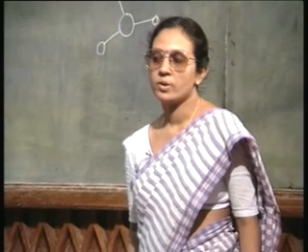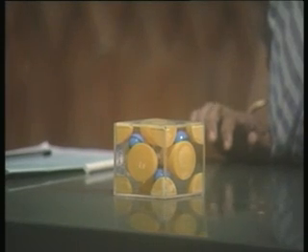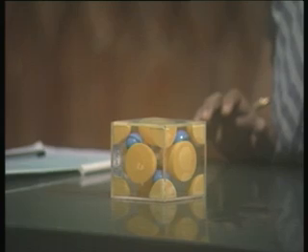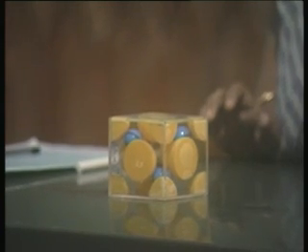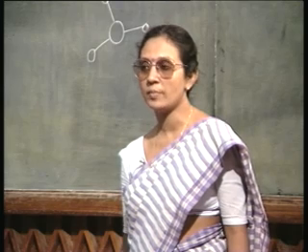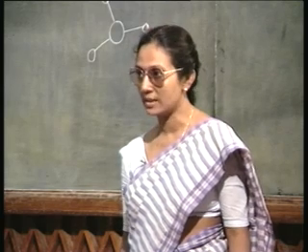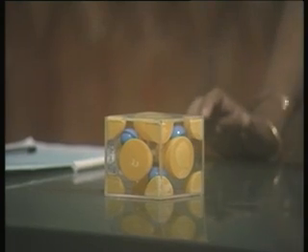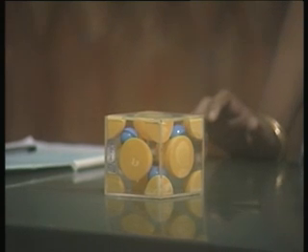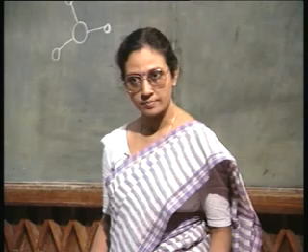You remember, we said that a diamond lattice or a zinc blende structure is quite loosely packed. The packing density is only 34% compared to an FCC structure where the packing density is quite high, greater than 70%. So, the packing density of a zinc blende structure is low. That means there is a lot of empty space within the crystal.